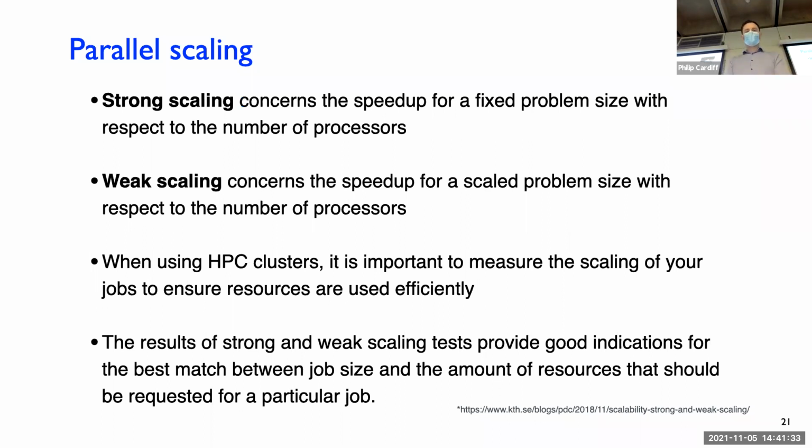Often it's useful to do a basic strong scaling study if you're really going to be using this, like for your thesis, which basically just means take your model and run it on 3 different numbers of cores. Run it on 20, 40, 80, or on 10, 20, 40, and then just plot how long it takes. If it's always getting faster, then maybe you can use more cores. It'll be more efficient for you. But if it's actually getting slower, then you're using too many cores and you need to reduce the number of cores. That's called a strong scaling study.